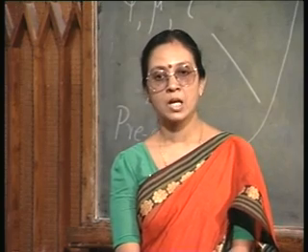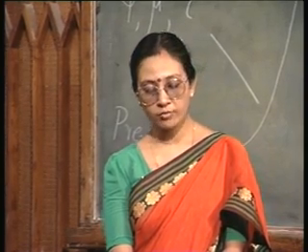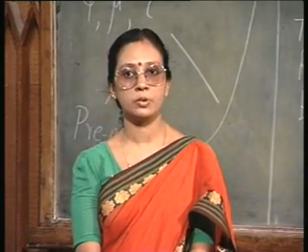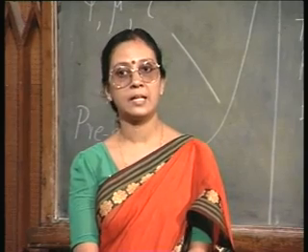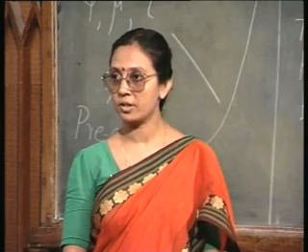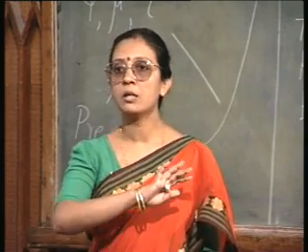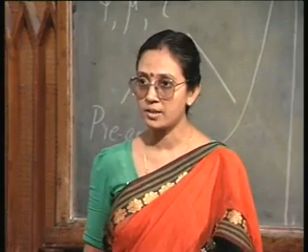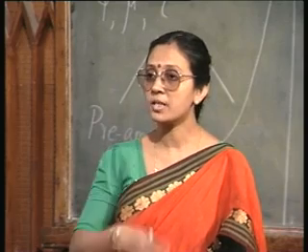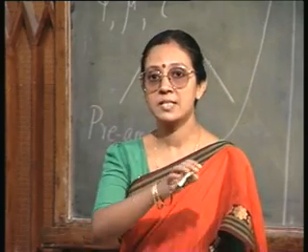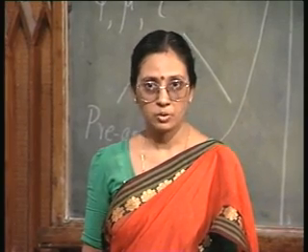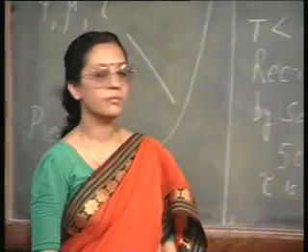That is because the activation energy of the substitutional impurities is much less than the energy of self diffusion. So, you can get back the carrier activation, you can push all the impurities in the substitutional site, but considerable damage is still remaining. You have not supplied enough energy for these self damages to get annealed out. So, tau is still very low.